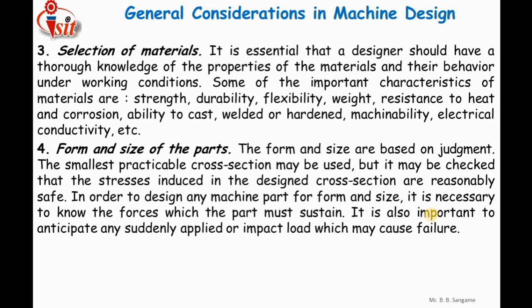So whatever the function of the component is, according to the design consideration, it should perform very well. It should not fail in working condition because of the loads acting on the component. So the design engineer should consider what kind of load is acting on the component. If the component will be safe for the smallest cross section, obviously it will be safe for the largest cross section of the same component. So while designing a machine, while selecting a form, shape and size of a part of any machine, a design engineer should consider whether the smallest cross section is safe or not.